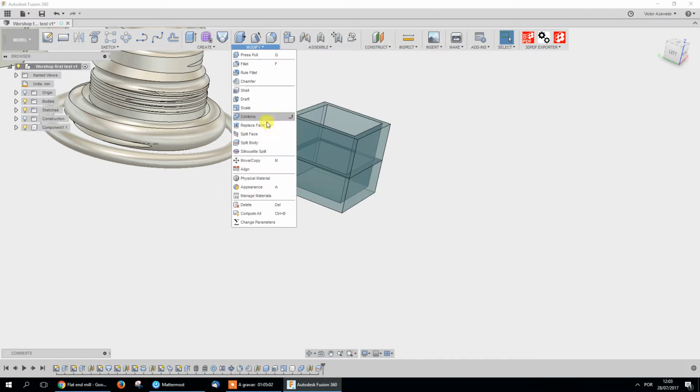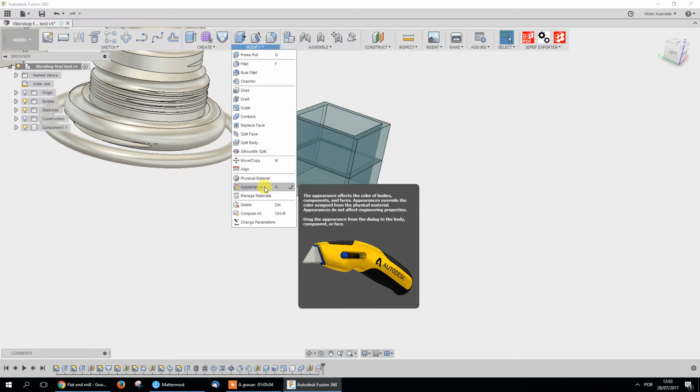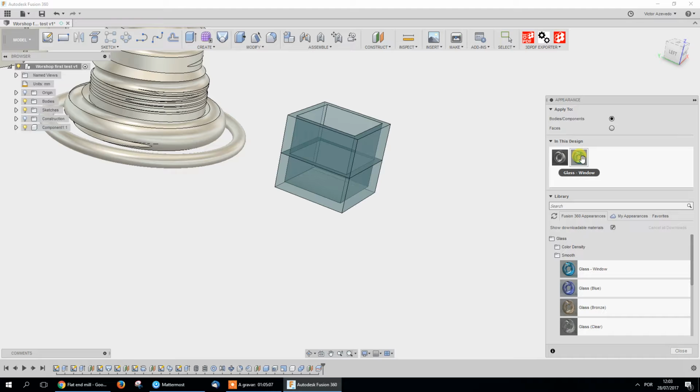So you can open appearance with the A. To modify, you can just right click and assign and delete. It removes the appearance. If you want to replace, you can also drag. It will add two, but will leave the last one. Why does it add two? Because you can define the properties of the material with one and the appearance with the other.